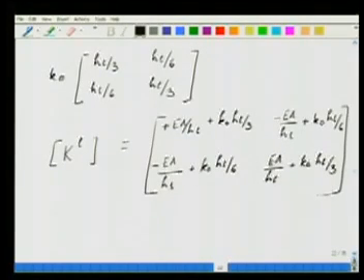Okay. So this is all the modification that has to be done to the stiffness matrix. Curiously, in this case, the problem with forces at the two ends will have no problem as far as the solution is concerned, because in this case the global stiffness matrix is invertible because there is no rigid mode. Because if you had a rigid displacement, it would lead to deformation of the springs, so the energy of the system is not going to be 0.